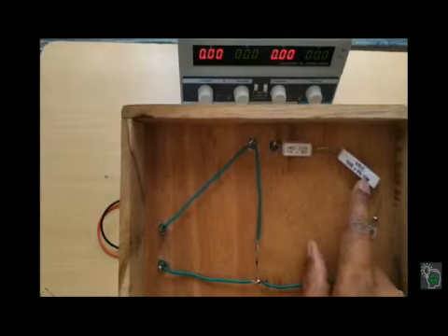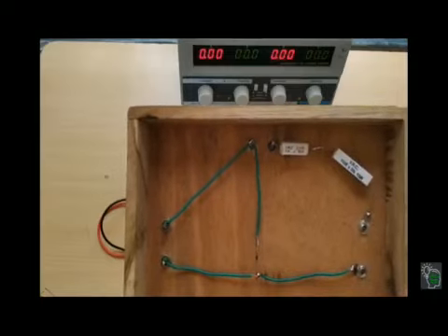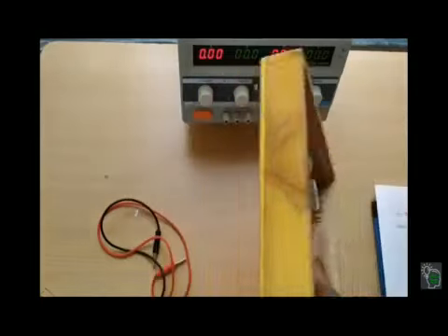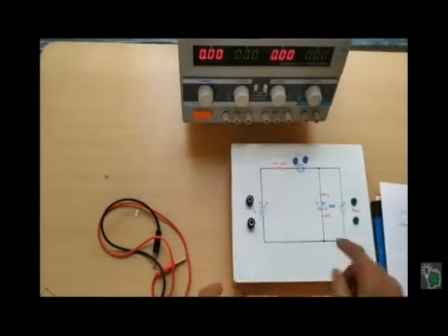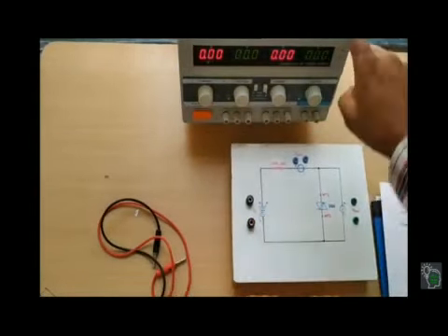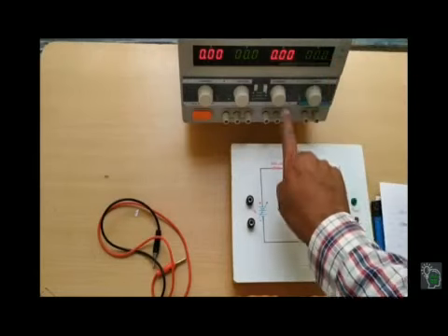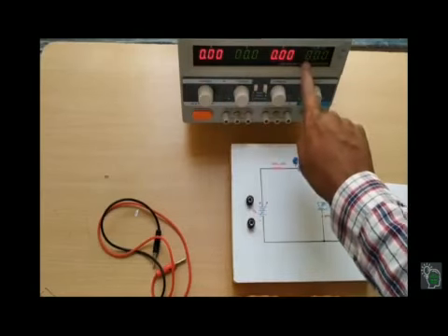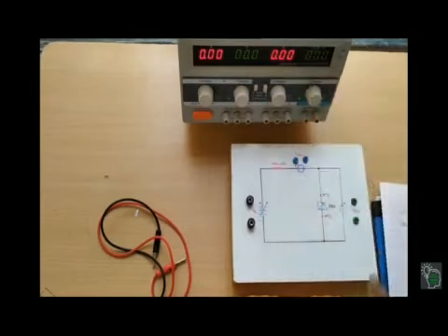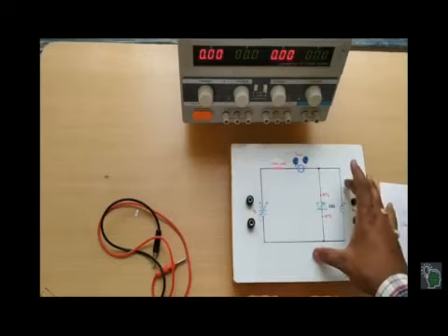Connecting in the circuit, let's start the connection. Here Diac is triggering around 32 to 36 volt, so we are having here 32 volt power supply. So using the series connection, we are doing the connection.